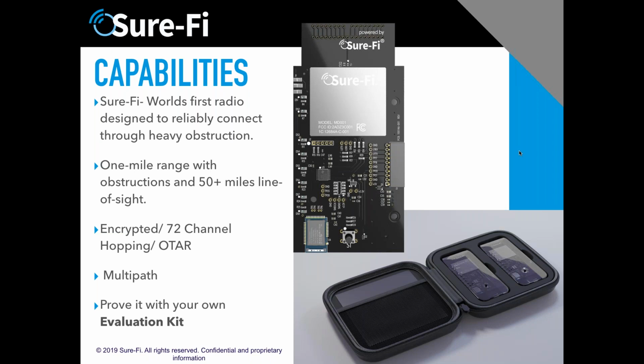Mario asked about a WLAN transmission point. I hope I answered your question, Mario. This is not Wi-Fi, and it's definitely point to point. It's 900 megahertz and, more importantly, chirp spread spectrum technology, which is what makes it so reliable. Bandwidth capacity: we probably need to talk a little bit about that, Mario, because it depends on the application, with the different chirp modulations and things like that.